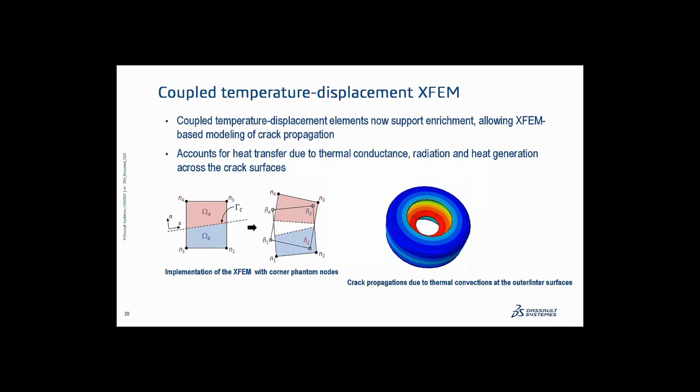We've now extended the XFEM implementation to include heat transfer, including thermal conductance and radiation across the evolving crack interface. So as the crack forms, surfaces are exposed, and you can capture thermal effects across those interfaces, in addition to structural effects like friction, which have been available for several releases now with XFEM.